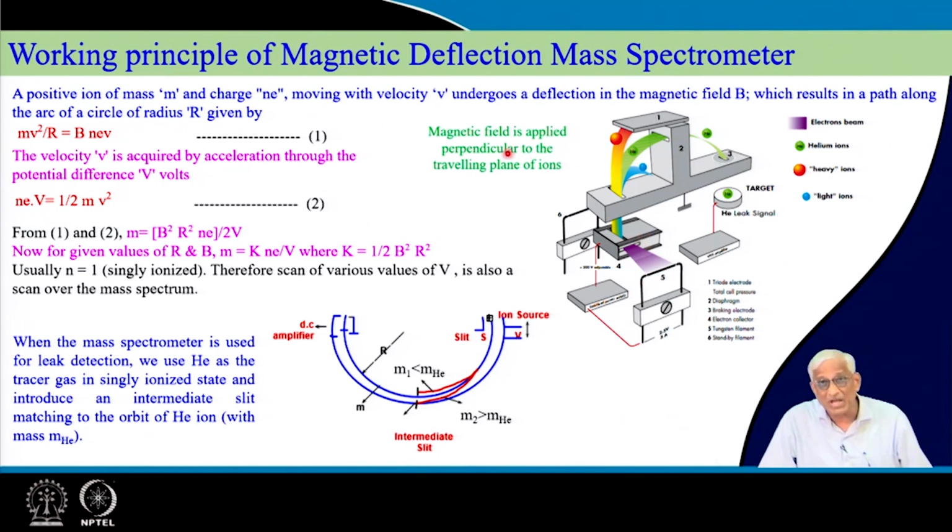and because the entire equipment is under vacuum chamber, it is only a zoomed version of the instrument. This whole thing is the detector, it is integrated with the vacuum system which we are trying to analyze. So, that way it is a part of the vacuum system. So, ions are created because these electrons are accelerated, they are getting high velocity, they ionize it. Once these ions are created, they are coming out with constant voltage selectors, velocity selectors, they are all there as